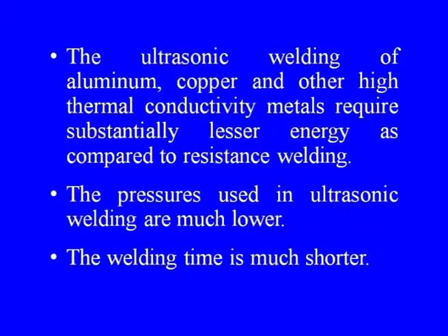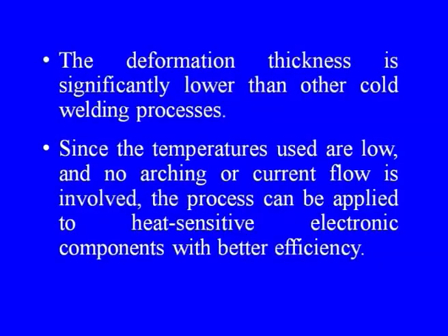The pressures used in ultrasonic welding are much lower. This is also another advantage of this process. Since the pressure requirement is less, therefore, the fixtures to be used need not be very complicated or very heavy in construction. The welding time is also much shorter relative to many other welding processes. The deformation thickness is significantly lower than other cold welding processes.